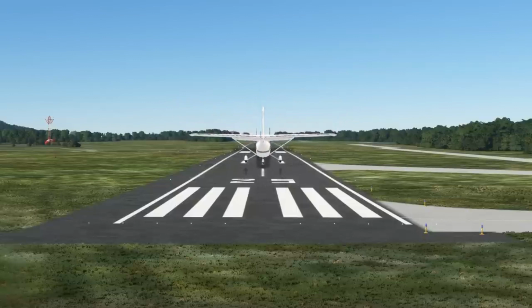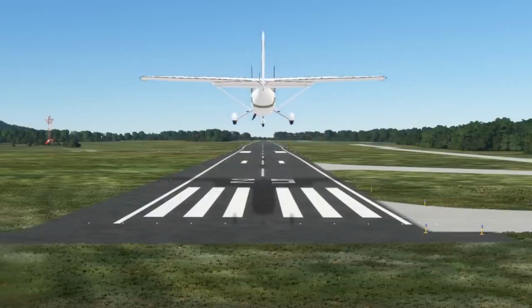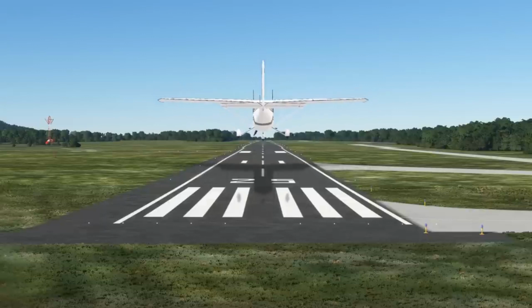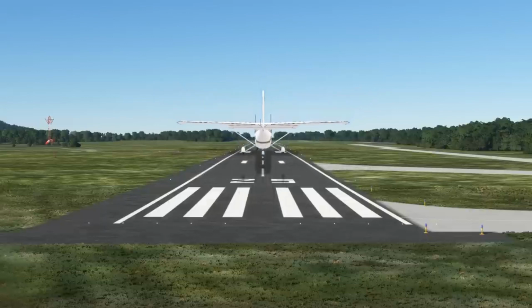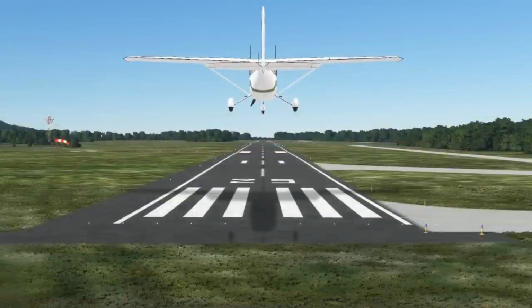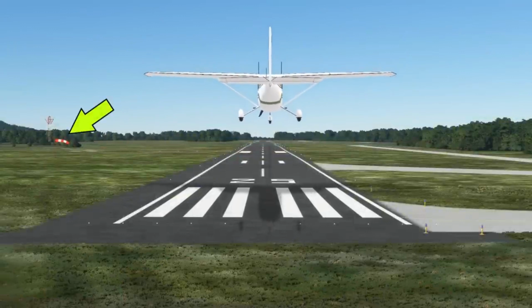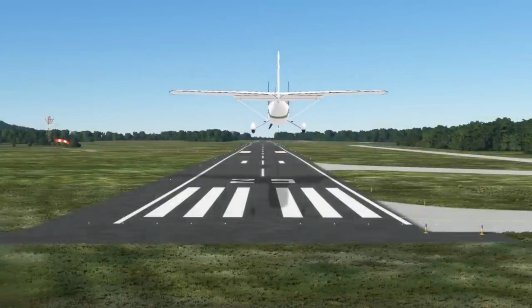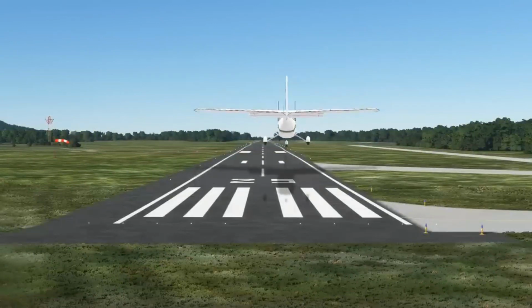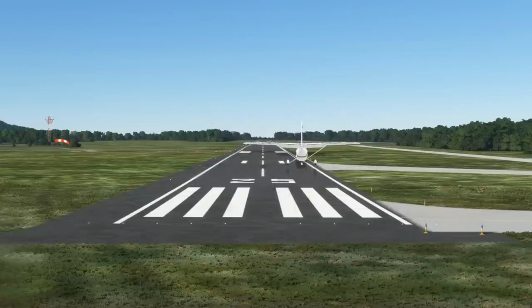During gusty or high wind conditions, prompt adjustments are made in the crosswind correction to assure that the airplane does not drift as the airplane touches down. As the forward momentum decreases after initial contact, the weight of the airplane causes the downwind main wheel to gradually settle onto the runway. End of page 9-17.